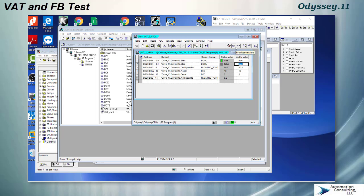Depending on which way you look at it, this is a normally closed contact. So we're going to modify it, and you can see here our actual speed ramped up pretty quick, and that's because our acceleration is set at 10 and my deceleration is set at 2. So watch how slowly this ramps down when I turn this bit off. So put a 0 here, shoot an off into it, and you can see it slows down slowly.